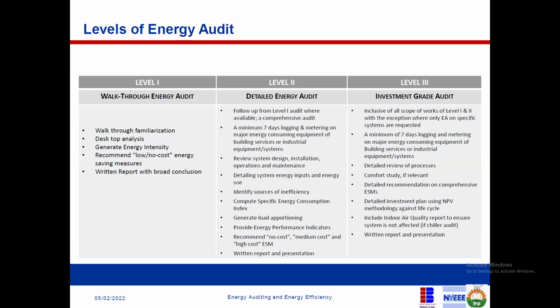Like in my house, I advise them not to do ironing or use the washing machine during the night. They have to use it during the day when I know that solar is on and the sun is up in the air. And I pump water, of course. That one is a must. I must pump water between the hours of 10 o'clock and 3 o'clock. We don't pump water at night because it means you're taking power from the battery, and that is not too good. So you can see I'm not buying anything new, but rather I am recommending no cost energy saving measures. So do this, don't do this, change this, don't do that, and then your energy will come down.